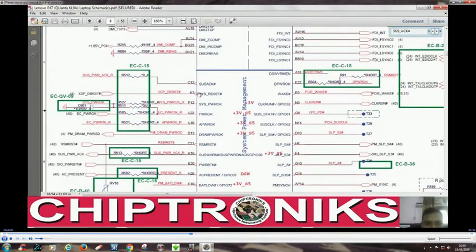And you can see this SUS_ACK. SUS_ACK is SUS_PWR_ACK_R. Now from where is this coming? It must be coming from the IO controller. So this is in fact tied up with this SUS_ACK.